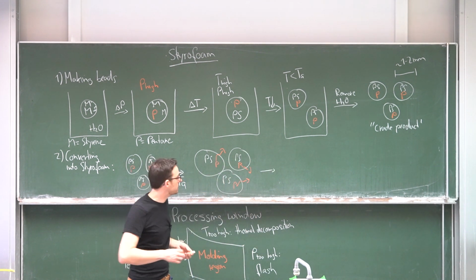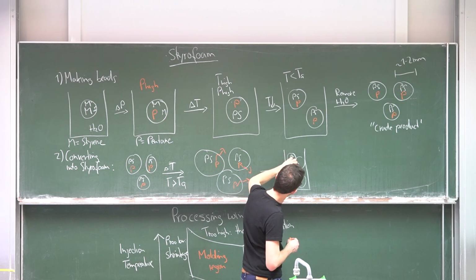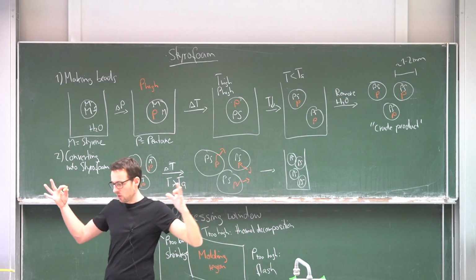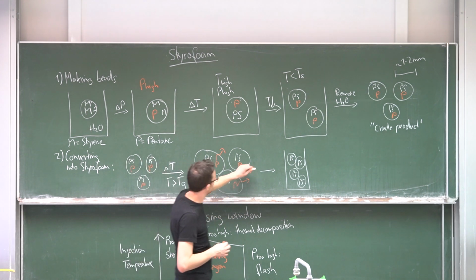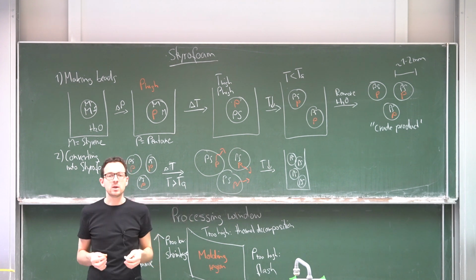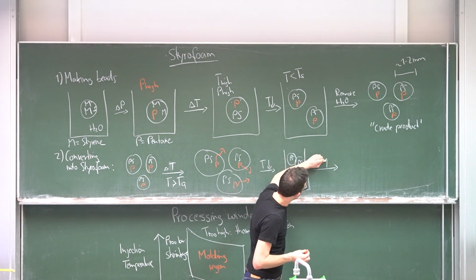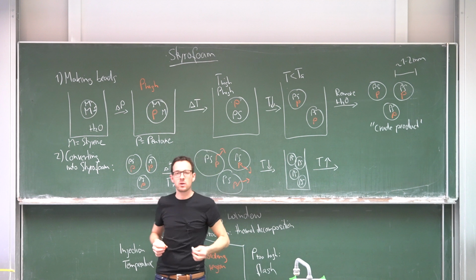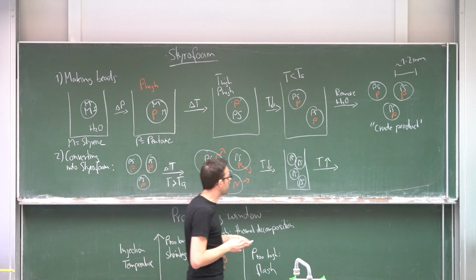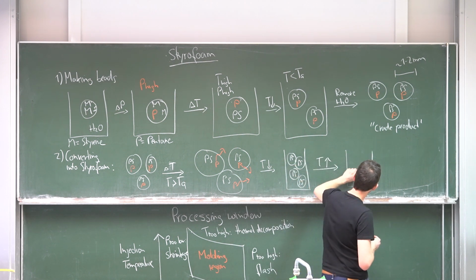just foamed up materials. And now we fill it into a form. Compress in the way that we want. So here the temperature can also go down again. It doesn't really matter because now we have this puffed up very soft and lightweight material. We fill it in the form and we increase the temperature again and push together our form into the desired shape that we want. And as we do this, we now partially sinter together our polystyrene beads.